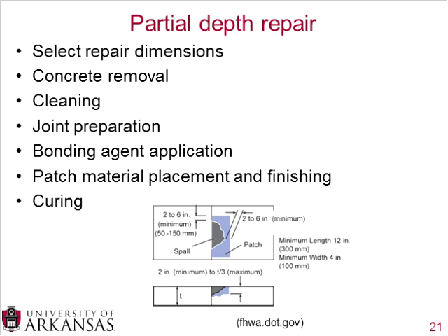Often these patches occur along a joint, so if you are putting a patch in along a joint, you want to make sure that you prepare the joint properly and that's all lined up before putting that patch in. If it is right next to a joint, you don't want that patch touching the other slab. You'll actually need a little bit of space there so you can put your new joint in, and the slabs can move and expand and contract as necessary.